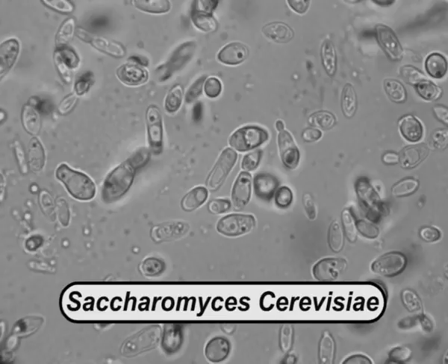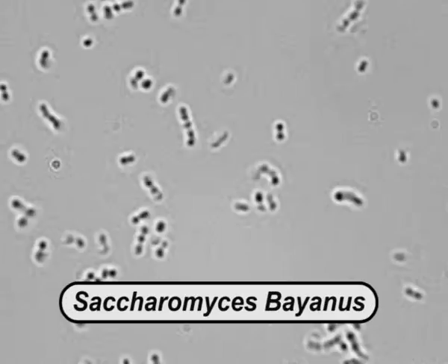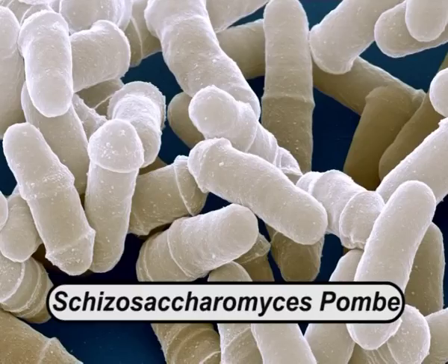Formerly, adventitious yeast were used to effect fermentation, but nowadays pure cultures of Saccharomyces cerevisiae, Saccharomyces bayanus and Schizosaccharomyces pombe are used. They are propagated from slopes by successively scaled up incubations using sucrose as the carbon source.